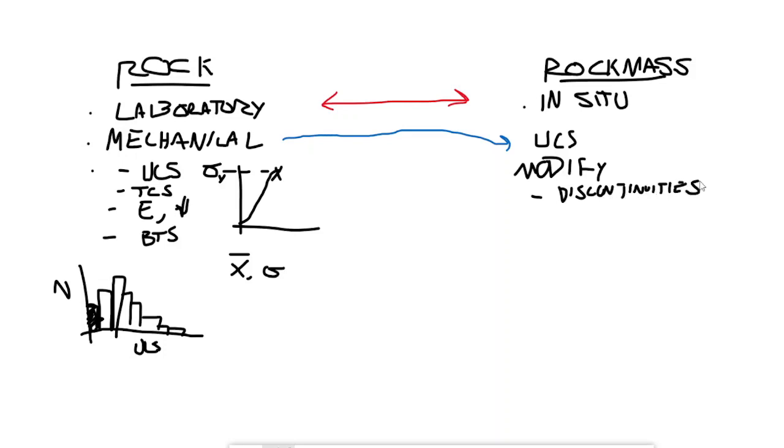Discontinuities is a general term for things like joints, joint sets, faults, fractures, anything where you have one slightly different unit of rock touching another unit of rock, or the same unit of rock that's just been forced apart, and maybe it's been altered around it, there's water in it, or some clay or talc infilling within it, right? So discontinuities are going to be a big one.